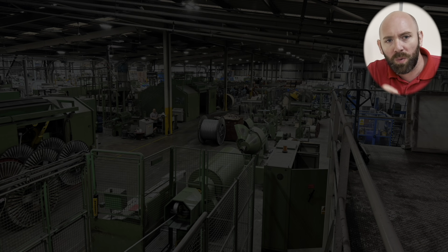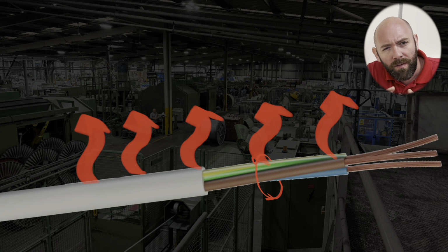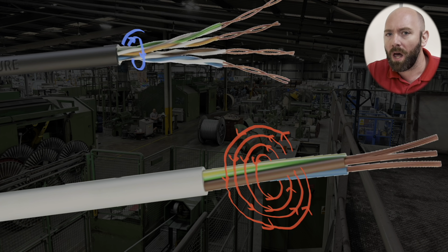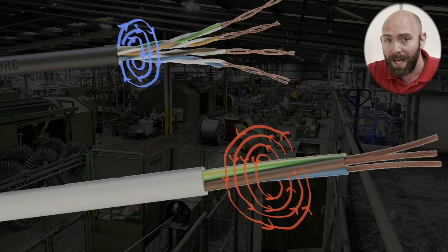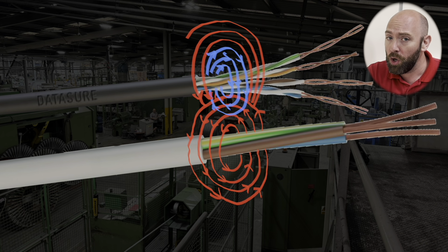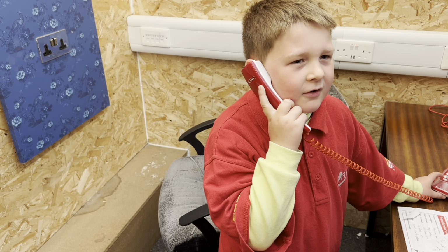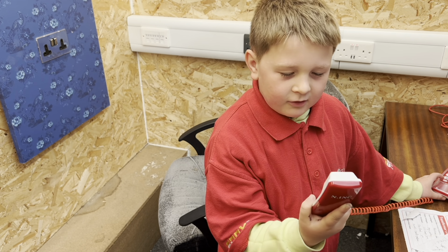So why can't we combine band 1 cables with band 2? Well, it brings us back to a couple of things which happen when you push current through a cable. It heats up and it creates a magnetic field. The higher voltage of the band 2 will create a larger magnetic field than the band 1, as we can see here. If we bring these conductors next to each other, we can see that the electromagnetic field from the higher voltage cable could interfere with the extra low voltage cable. This creates interference in the band 1 cable, and if it was a communication cable, we could, well, lose communication.